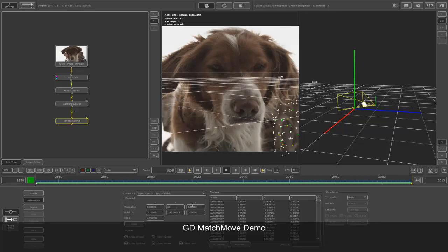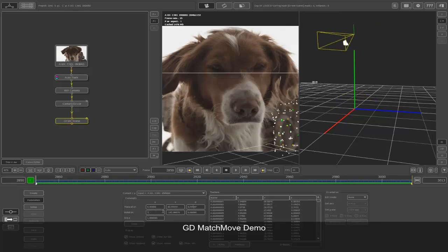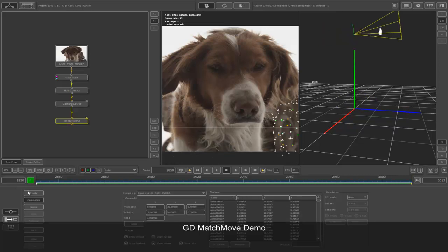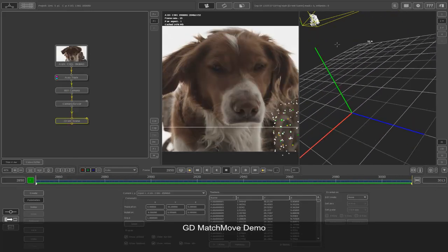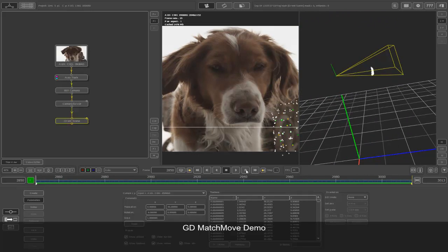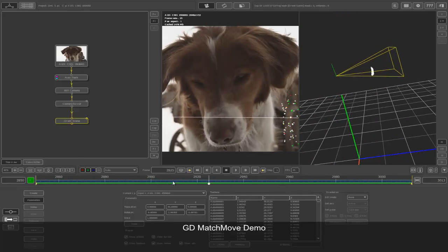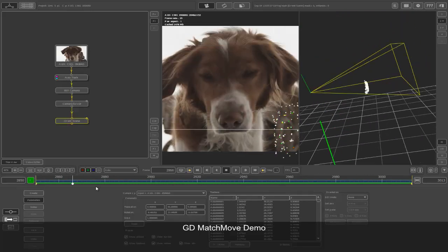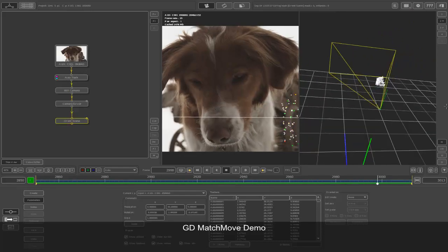So 30 on this, nothing on this, minus 8-degree tilt over here, and nothing on Y and nothing on Z. And I did it in the first frame, so because of which it's not keyframed anywhere else, and I have the values directly in. And the best thing is you can see that the camera is tracked, the camera is moving in the 3D view,